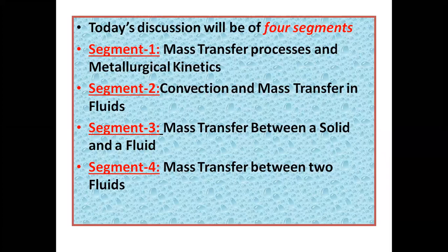When it is maintained, what happens? Carbon contacts the Fe2O3 on the surface of the iron ore and picks up oxygen from it, leaving oxygen deficient iron ore: Fe2O3 to Fe3O4, oxygen deficient, Fe3O4 to FeO, oxygen deficient, FeO to Fe. That means gradually oxygen from the iron ore is leaving the place, mass transfer taking place. That oxygen is taken out by carbon in the form of mono or dioxide, and they escape out.